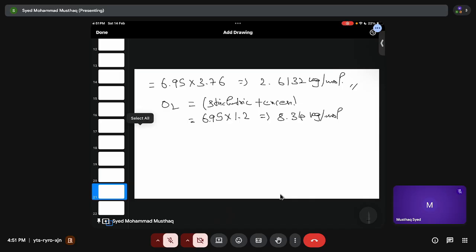So for example, everything gets combusted. Okay, combustion is done. So the oxygen that remained in my products of combustion will be... See, excess air is only supplied to increase the interaction between the fuel and air. It's not that we give excess air to burn. Whatever oxygen is required, that is only getting converted and reacted. Whatever excess is there, it will still remain. It will not react.